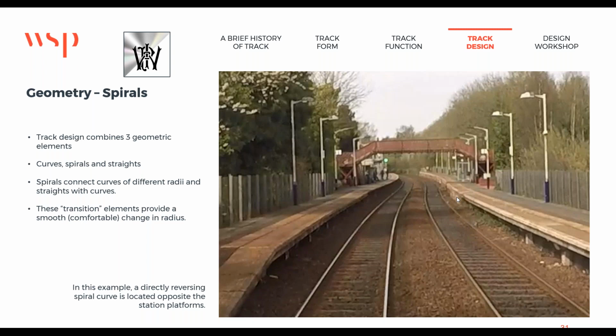Regular tamping solves it, but if you're going to have track fault problems, or repeat track fault problems, I would look at other influences and think, okay, why have I only got problems in that half of the platform? Why is it only this end of Giffnock Station that's giving me the issues? Well, that's where the platform riser wall changes on the side. So maybe that's giving me a change in stiffness.